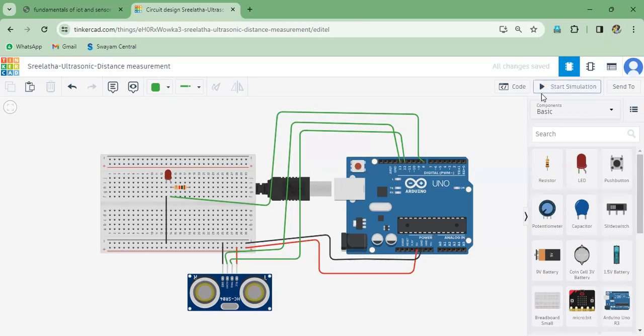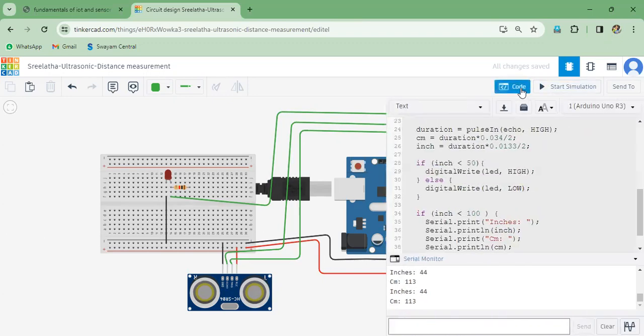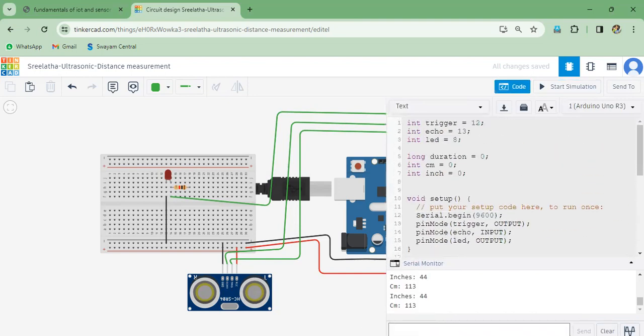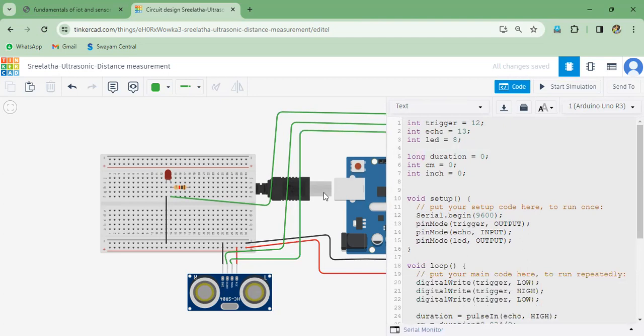according to the movement detection. Now we will see our code so that you can understand clearly how we do all these things. Okay. So here, as we know that we have trigger and echo pins, and these are digital pins, I have given 12 and 13. It's your choice. You can vary from 0 to 13. You can go for 9, 10, 11, 12, whatever. Then coming to the LED, I have given pin 8. Any pin number you can apply for this LED.